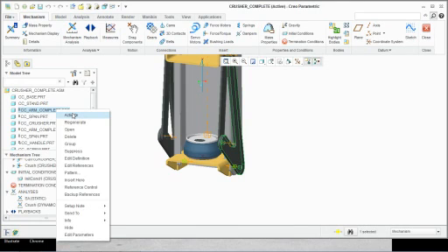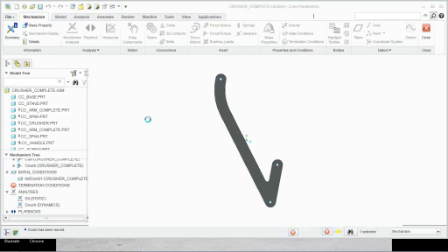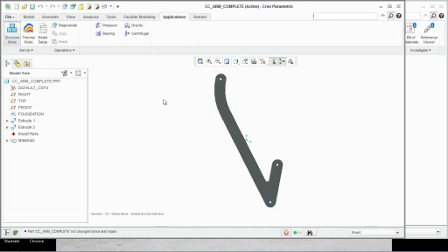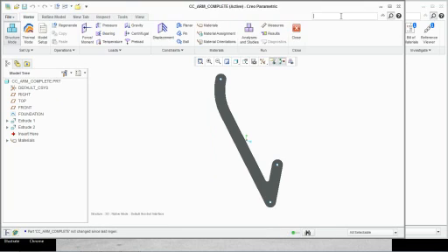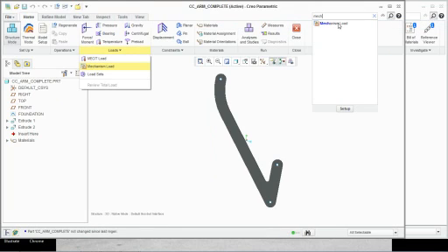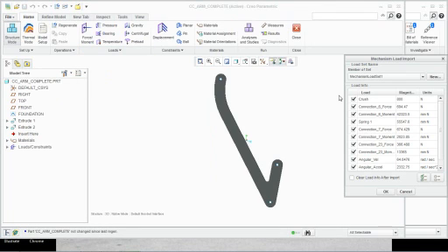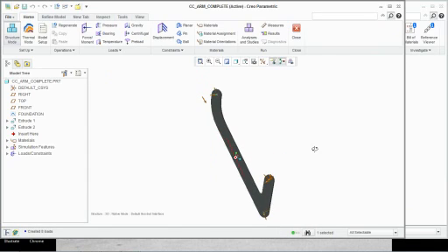You can also go into Creo Simulate, and we can look for mechanism load. See that right there? And we can import all these loads. So you see all those loads are automatically applied to the part. We can add our constraints, material properties, all that good jazz, and run a static analysis or different types of FEA analysis that we might want to run.